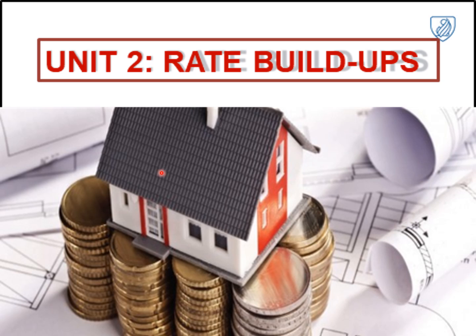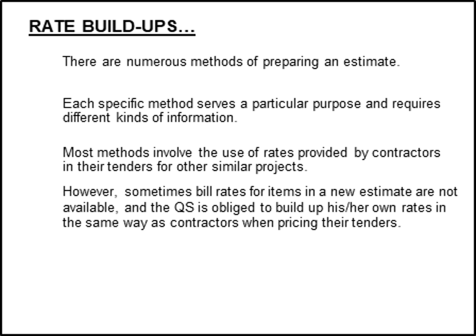Rate buildups. This goes hand in hand with your elemental estimate and is a way to approach it. The example that was provided will give you the structure, but you always have to refer back to your elemental guide on what is included and what's not included in your elemental estimate and, subsequently, your rate buildup. The main thing about rate buildups is that you're taking existing rates and amending them to be in the correct unit for your estimate.